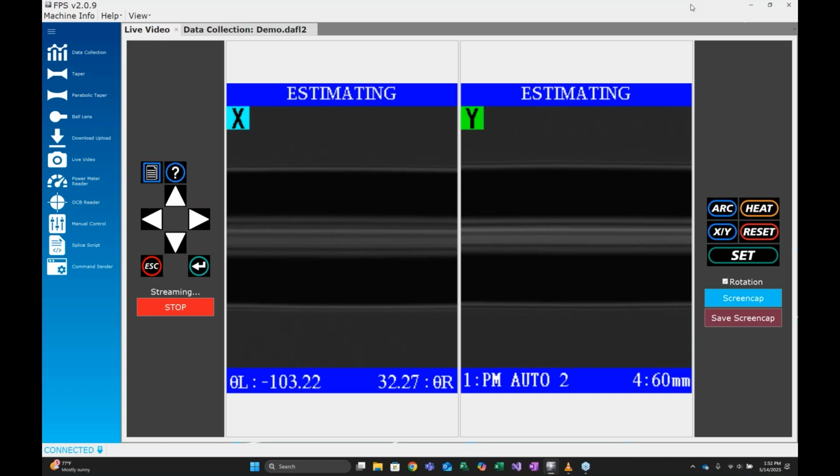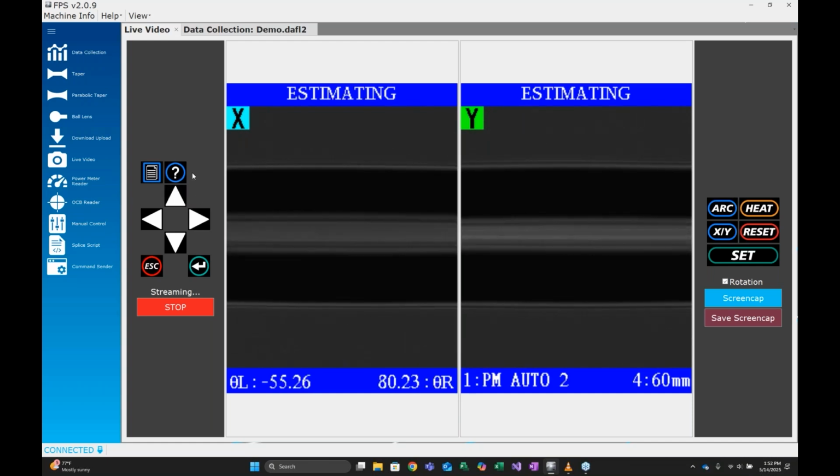So the LED power, I'm assuming this is during end view imaging. I did touch on this very briefly, but if you're in the end view alignment state, where you're looking at the end of the fiber, if you hit the question mark, it'll toggle the controls for the end view alignment.